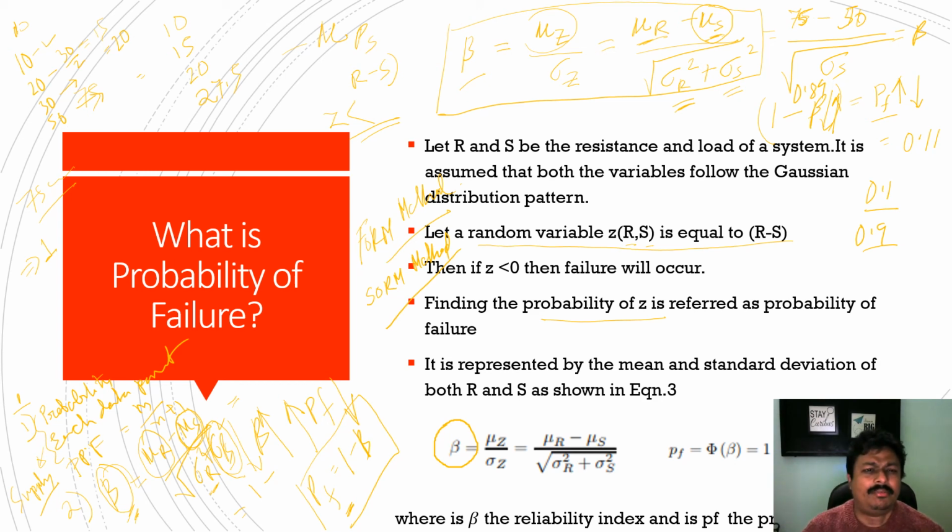Okay, so these are all random example points, so there can be some mistakes, but more or less this is what it is. Moving average of this data point is this, right? After that, you use the SORM method. That means you find the probability of these data points, right? You find the mean of the probability, then you put it into this equation, right? And then you find out the beta, and from beta you find out the probability of failure.